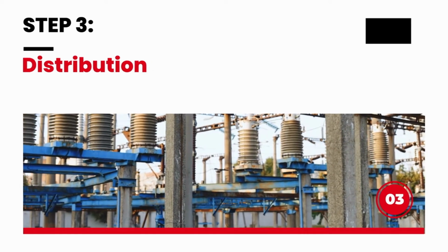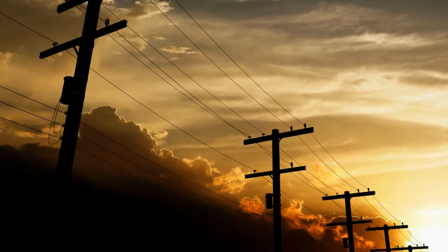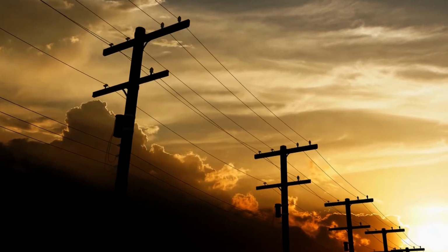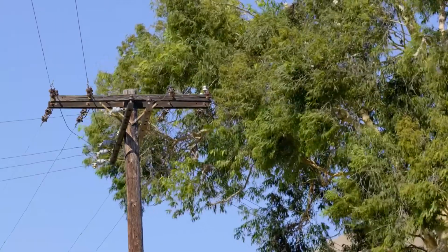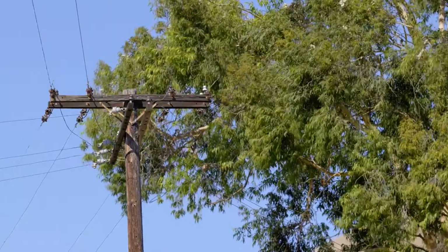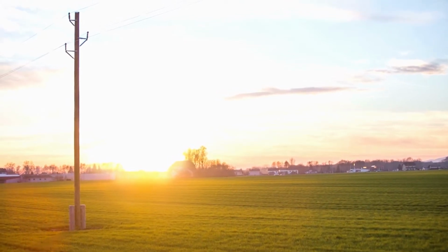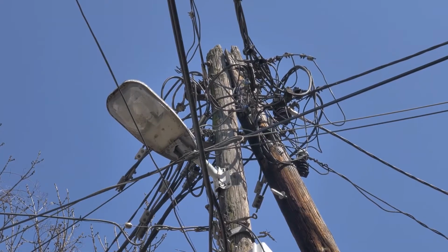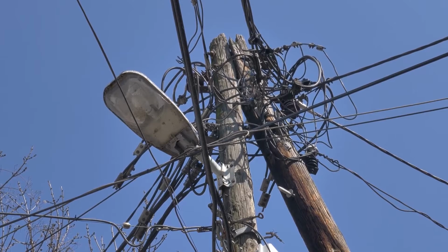A distribution system is the final step to delivering power to customers. A distribution substation energizes the distribution system that supplies power to customers. Distribution substations contain power transformers that step down the high transmission or sub-transmission line voltage to the primary distribution voltage. Most utilities operate their distribution system between 4 kilovolts and 34.5 kilovolts. Circuit breakers for switching individual distribution circuits are typically installed at these stations.